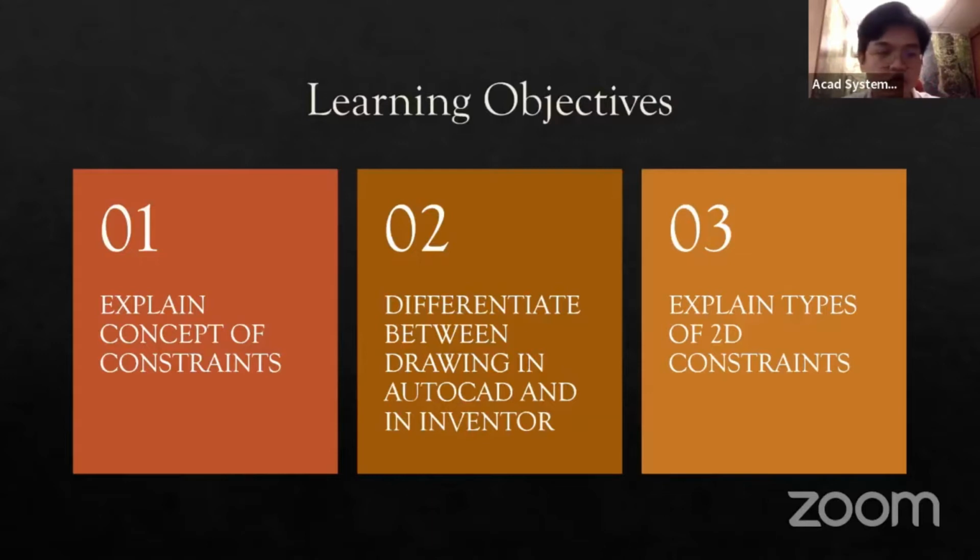So what are constraints? Mainly, 2D constraints limit changes, as well as define a shape within your sketch. So in the case where, let's say, you constrain your line horizontally, no matter what changes you make, the line will not be angled or vertical. It will stay horizontal. However, if you move it, you can move it vertically or horizontally.